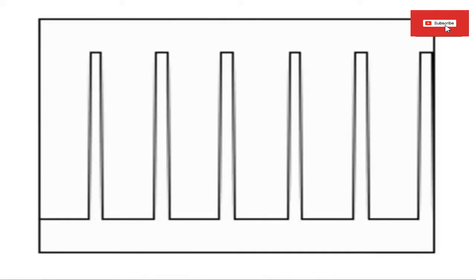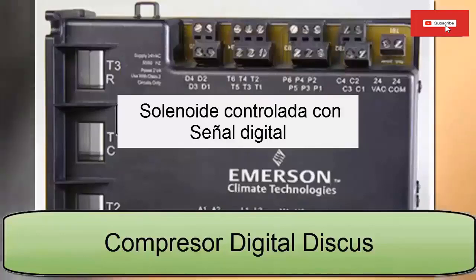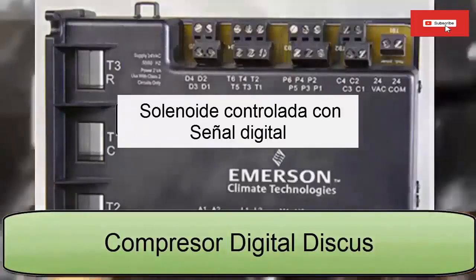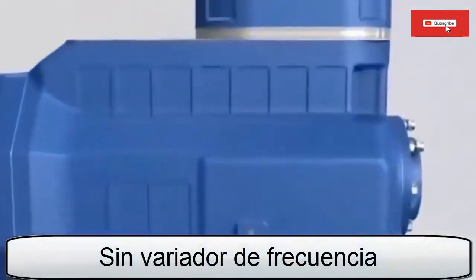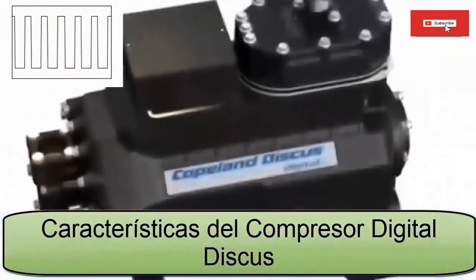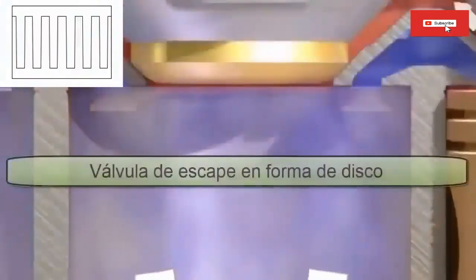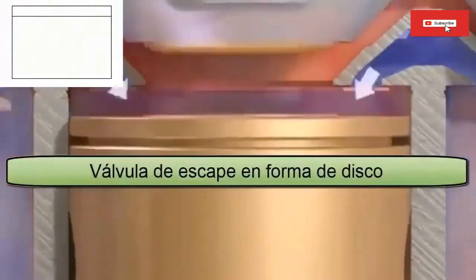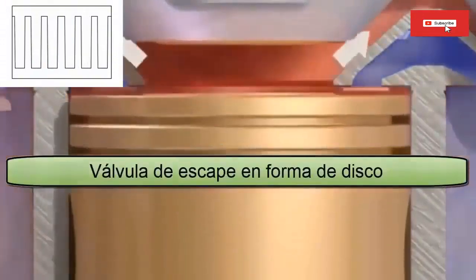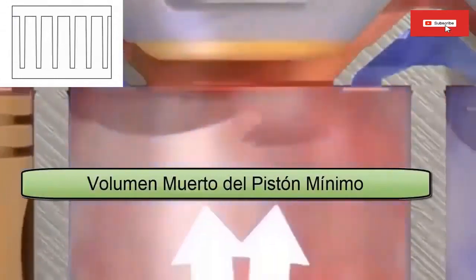We are going to look at Copeland's range of digital type reciprocating compressors known as digital discus. Let's start by saying that this range of reciprocating compressors has 3 cylinders with continuous capacity modulation, without a frequency inverter. The characteristics of the digital discus compressor are: 1. The 3-cylinder digital discus series compressors are an alternative to a variable frequency drive to achieve continuous capacity modulation. 2. Digital modulation is the simplest and most accurate method of controlling reciprocating compressor capacity with the least applied cost.